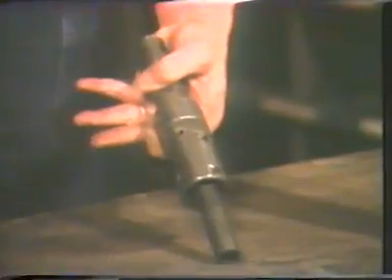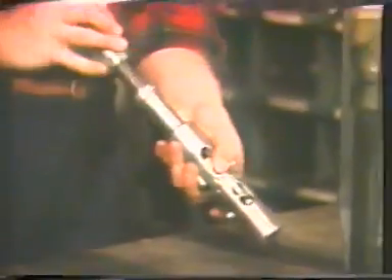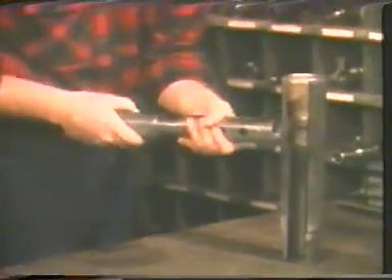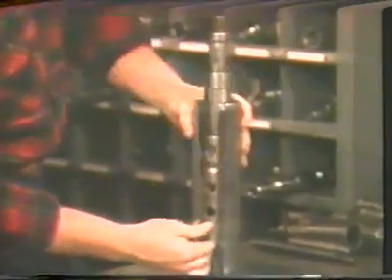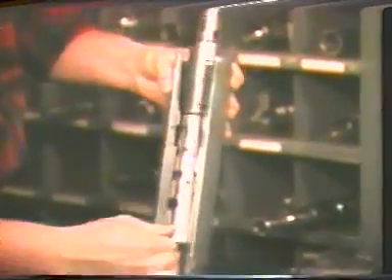Without the locator ring on the running tool, the lock may be run below the desired nipple and pulled up to it, allowing the up-facing locking dogs to locate the nipple. After locating the nipple, the same setting sequence is followed.